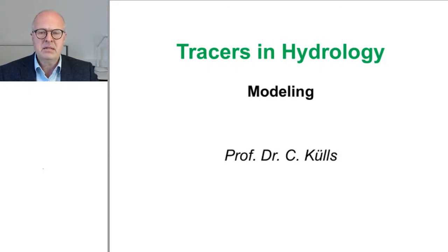Now, the case is a bit complicated because we have surface water on the one hand and groundwater on the other hand. The notion that we work in a swamp involves that maybe we have water of high acidity, in that case lower pH. And which tracers do we choose? For surface water, uranine would not be perfect. We know that eosine has a low pH dependency, but it is also light sensitive.